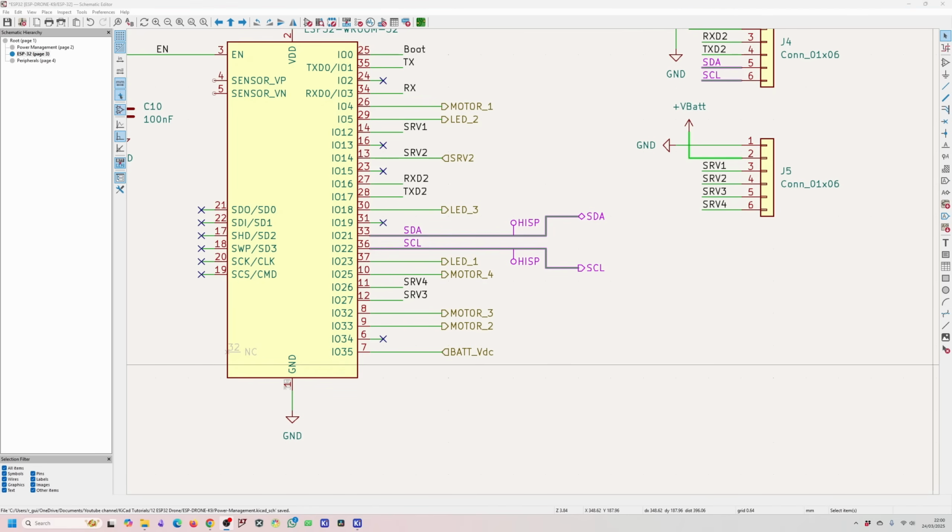So in summary, if you're not using net classes already, I think you should be, especially for more complex designs. Obviously, if you're designing a very simple PCB, then you don't need to use net classes at all. When it gets to a more complex project, I think you should always use net classes to manage your track widths and your design rules, to improve consistency, save time, reduce errors, and help ensure that your board functions correctly at fabrication. So when we set up the rules, we are actively thinking about track thicknesses and things like that. So we want to make sure that we get them right.